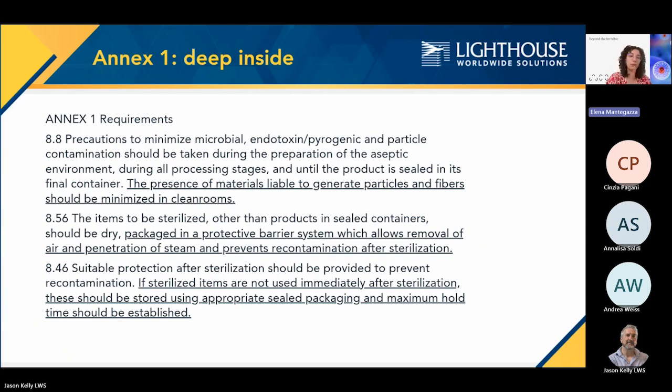Exactly. Here in this slide, I wanted to go a little bit inside the Annex 1. Here I have reported some paragraphs that are focusing on the topics that we will see in the presentation. So the first paragraph, the 8.8, contains a sentence that says, the presence of materials liable to generate particles and fibers should be minimized in clean rooms. So the first hint that Annex 1 gives us is that we have to reduce the possibility that the packaging adds particles.